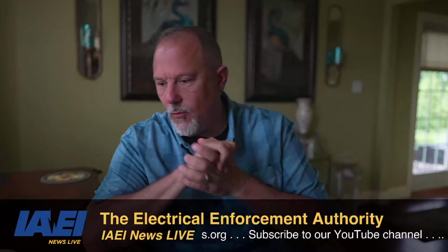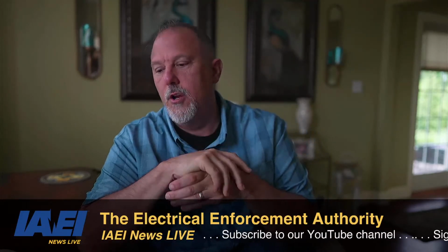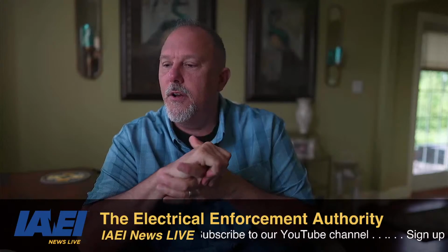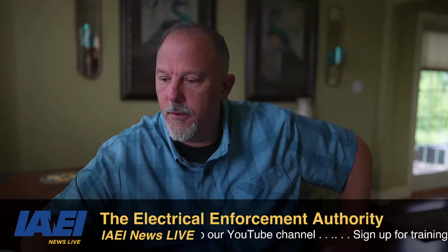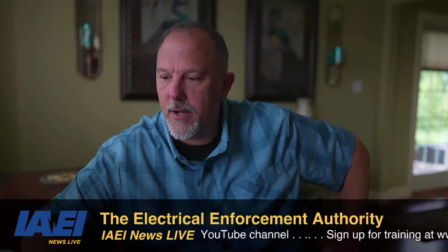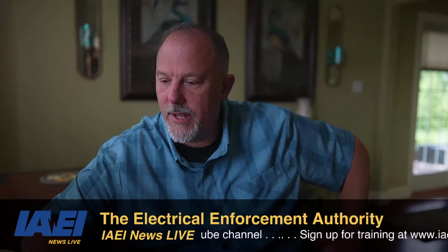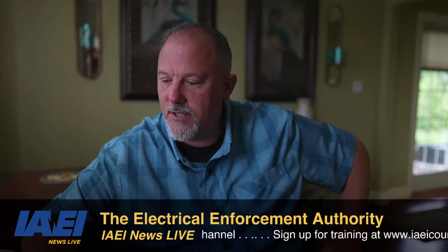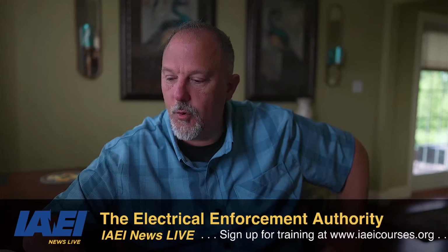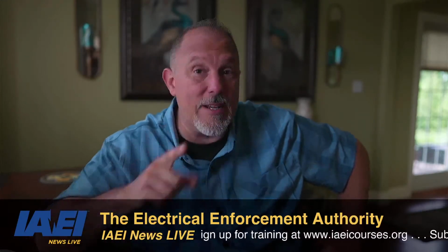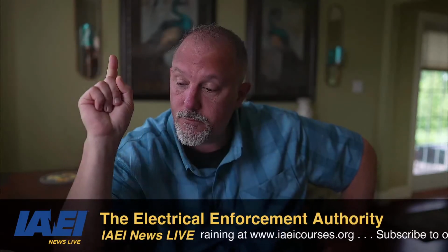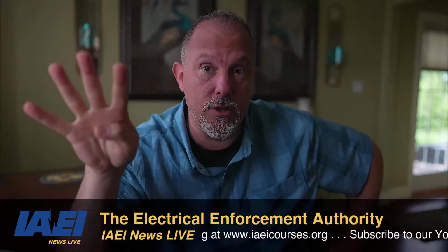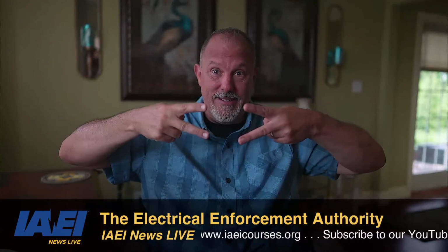Travis, I think you have one receptacle outlet and 4 receptacles, right? Michael Hoffman asks: 2 duplex receptacles in a 2-gang box, how many receptacle outlets? Hey, Nihad El Sharif, good to see you again. You have 1 receptacle outlet and 4 receptacles. Travis, I'm going to stop with you because I agree 100%. You have 1 receptacle outlet and you have 4 receptacles because you have 2 duplex.